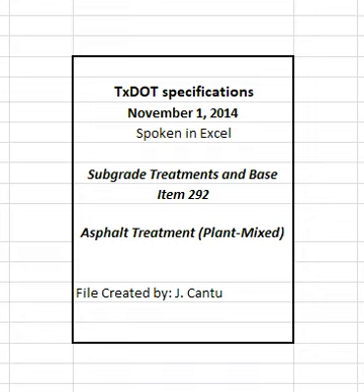4.1 Mixture design. Using TEX 126E and the materials proposed for the project, the engineer will determine the target asphalt content required to produce a mixture meeting the requirements in Table 4 for the grade shown on the plans. The gradation of the combined aggregates will be determined in accordance with TEX 200F, Part I.